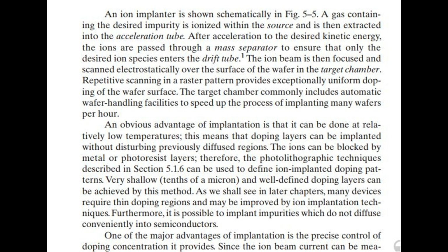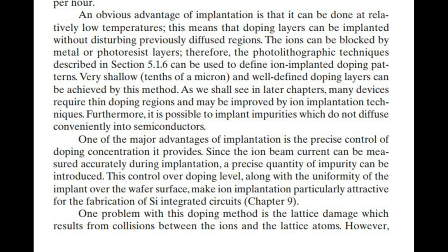One of the major advantages of implantation is the precise control of doping concentration it provides. Since the ion beam current can be measured accurately during implantation, a precise quantity of impurity can be introduced.